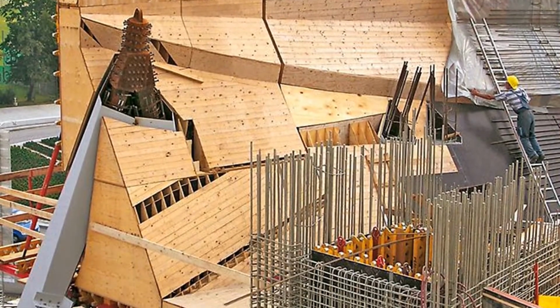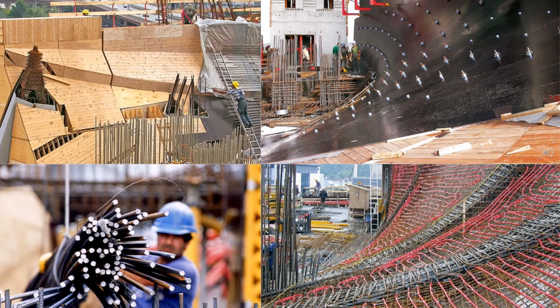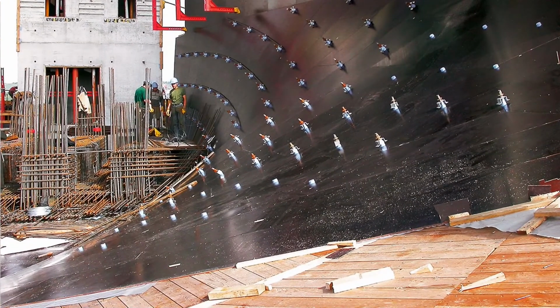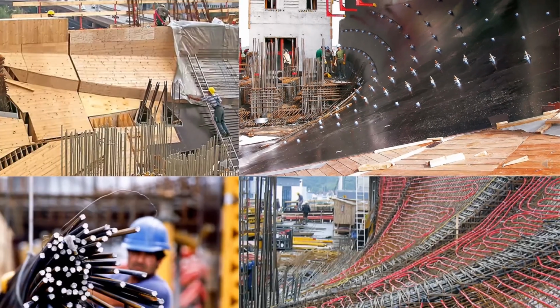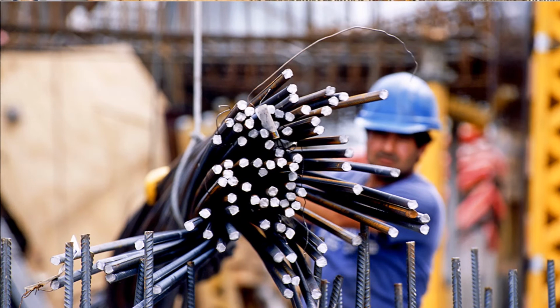Prefabricated formworks are positioned on the building site. And then, formwork panels with a watertight coating are laid out over the prefabricated formwork. Then, placing of reinforcement is made to reinforce the tensile strength of concrete.